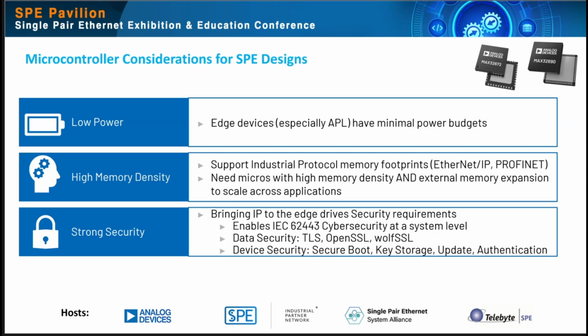You also have to be thinking of your power budget. So for Ethernet APL, do you have a low power microcontroller? Are you prepared for the power requirements that are driven by that use case? So we're powering your device from the single pair Ethernet line.